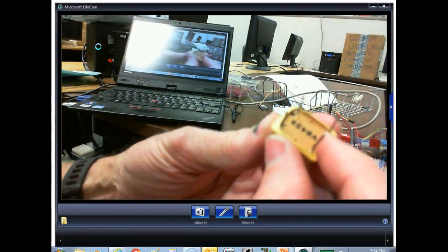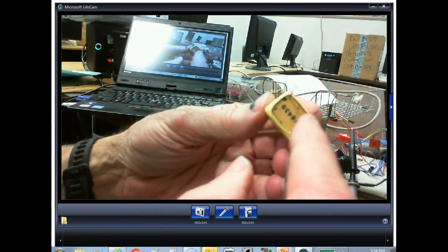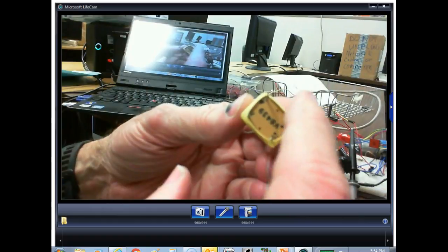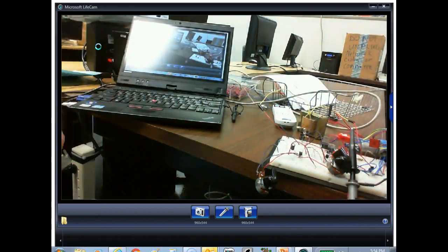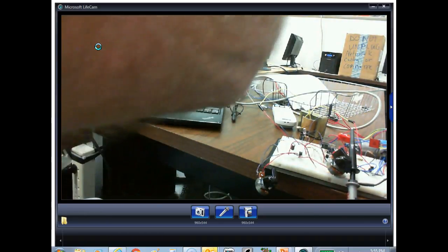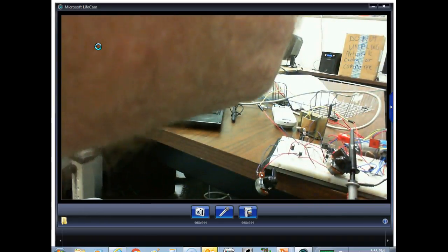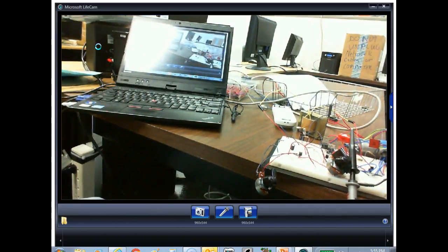It's got dots on here that give you the polarizing. It means if we hook this up right, if this is positive, this side right here would also be positive. That's what the dot means. Because if you hooked up the secondary backwards, the SCR would never fire, because it would be positive when the SCR is reverse biased. Y'all understand that? Because when you go through a transformer, you get a phase reversal.